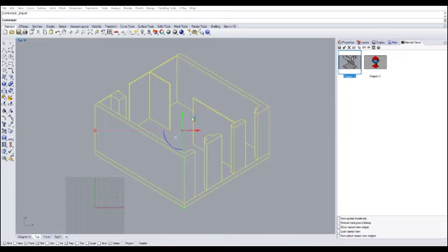So once again, 1/4 inch equals 1 foot, which is also 12 inches. So this is 1/4 inch equals 1 foot: 12 inches goes to 1 foot, and 1/4 inch is 1/4 inch. So this is ready to go and matching the scale that we have specified for our previous drawings of our survey plan. And then we're going to say OK. And then we're going to say Save, and it's going to ask you the same thing again. We're going to say OK.